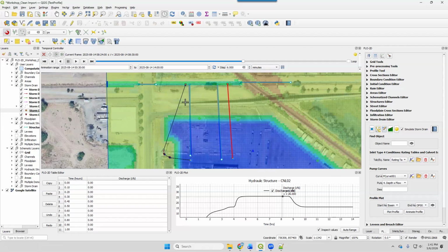So that, and why is that important? Okay, so this is very important. If this final conduit that's connected to this outfall doesn't have a positive slope, it might actually act like a sink and actually take water away from the surface right here. So instead of getting 10 CFS, you'll get 10 CFS removed. So that's why this always has to have a mildly positive slope, even if it's a bubble up. You don't want to have that be a negative slope.